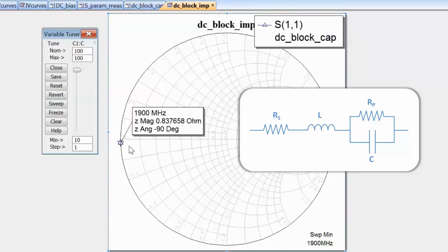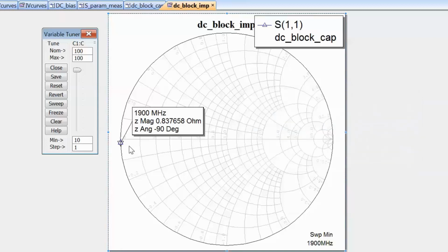So actually having a parasitic inductance as part of your real capacitor is not a bad thing, because it allows you to use this capacitor as a resonator effectively, and hence achieve very low impedance at your frequency of interest, although of course this is quite narrow band. The frequency at which your capacitor and the parasitic inductor associated with its construction resonate is called the self-resonant frequency. So ideally your DC blocking capacitor should be a capacitor whose self-resonant frequency is the frequency at which you're operating.